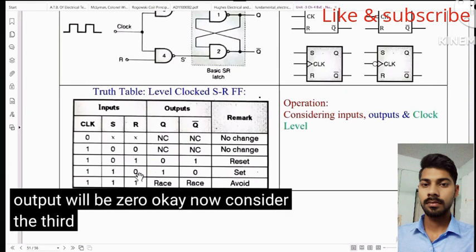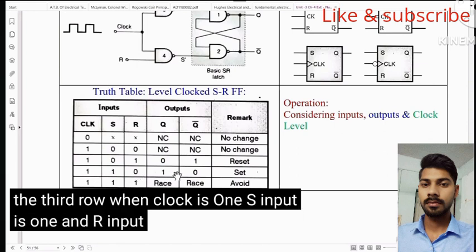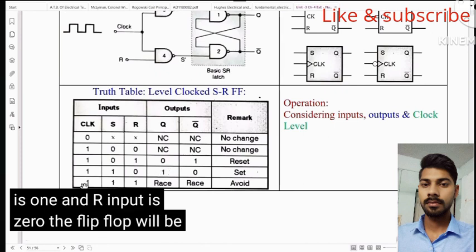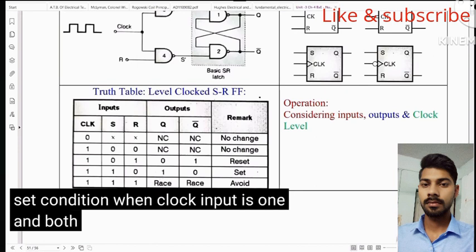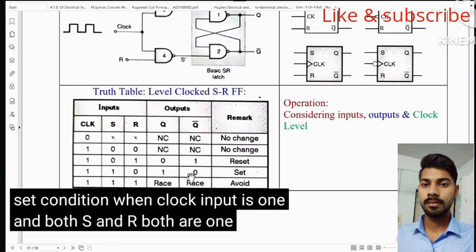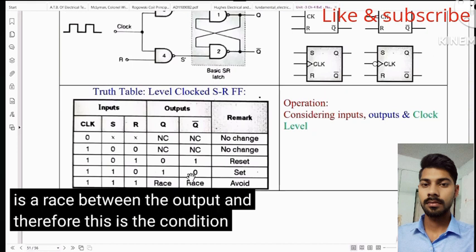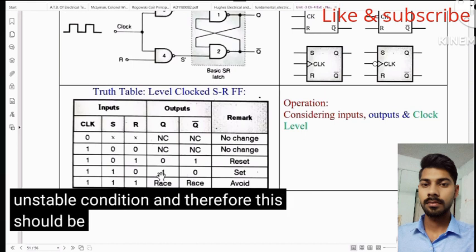Now consider the third row when clock is 1, S input is 1 and R input is 0. The flip-flop will be going in the set condition. When clock input is 1 and S and R both are 1, then there is a race between the output, and therefore this is the unstable condition and should be avoided.